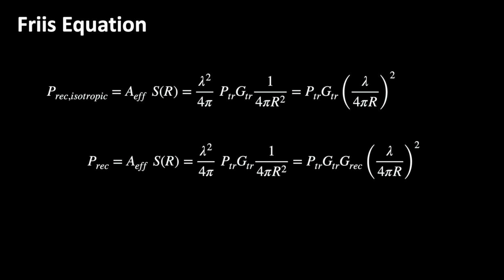But there is good news, at least for some cases. On higher frequencies, you can achieve a higher gain on the same antenna size. At a base station, we can use an antenna with higher gain, having the same dimensions, and this way the effect can be compensated.